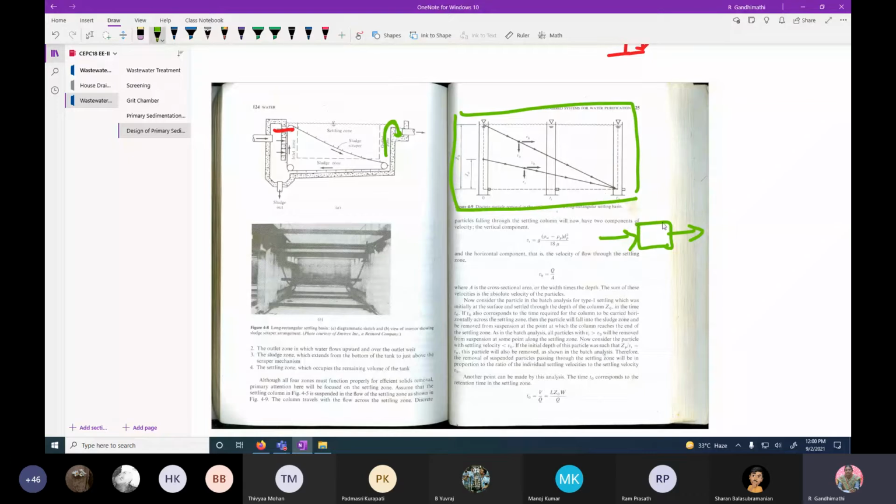system boundary. For example, this is the system. The primary sedimentation tank is one treatment system. Maybe you can draw an imaginary line. Here you can expect there is a mass transfer from outside to the inside. You are receiving the flow from the sewer that may be admitted into the primary sedimentation tank. After the detention time, the flow may leave the tank at the opposite end, and this is also continuous. Therefore, there is a mass transfer across the system boundary, that is called continuous flow. Now, whatever I have explained here is with the continuous flow.